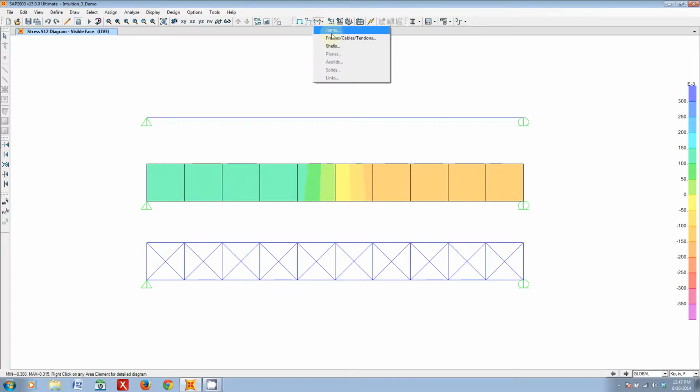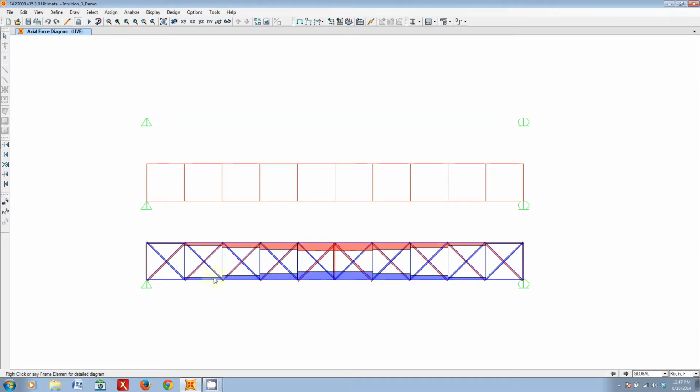Now what does this look like if we were to look at this in our truss? Let's check out the axial force diagram for our truss, and this is really cool. You can use an interesting heuristic that says that the shear in a beam is carried by the tendons or the webbings of a truss. Well, what does that mean? Let's say we had that constant negative shear on this left-hand side. We would expect that the forces in our members, or more specifically the forces in our tendons, would remain constant because the shear force is constant. And indeed that is the case. Check it out. All of these tendons carry more or less, visually it appears, the same load.